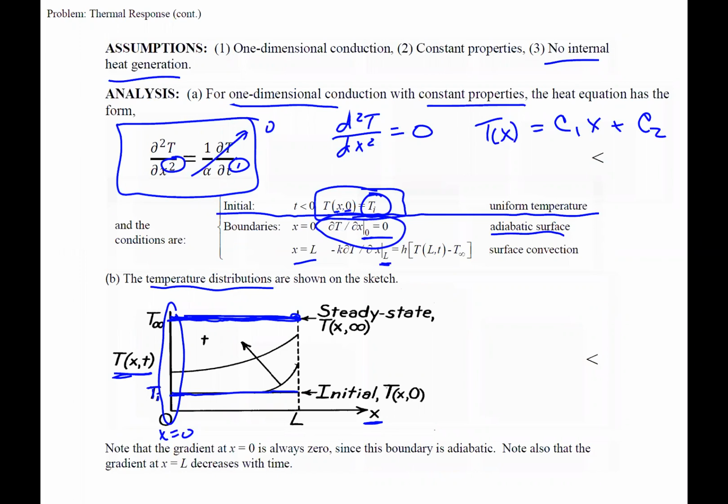Then we need our 2 intermediate times, right? They chose those ones, you can draw at different times, but you want to space them out. We start with the first one here. We play it off with understanding the boundary conditions, what's going on, to determine how to draw the line. The easy one I like to start with is we know the left side has to be a slope of 0 for the temperature distribution. So we have slope of 0, slope of 0, slope of 0.